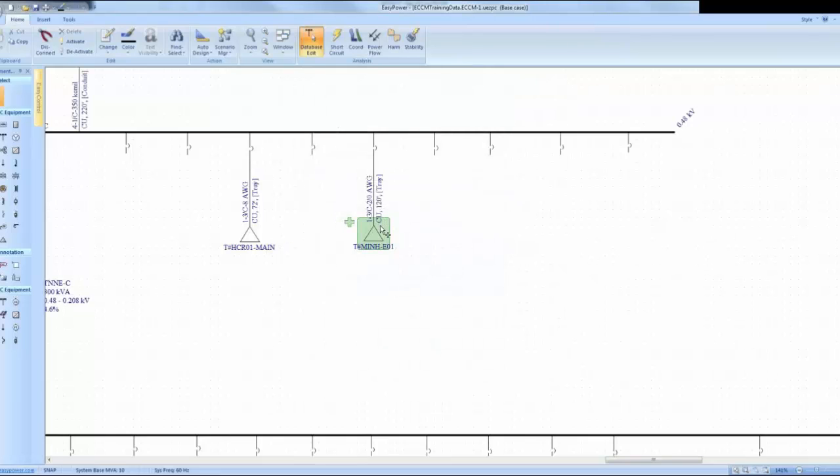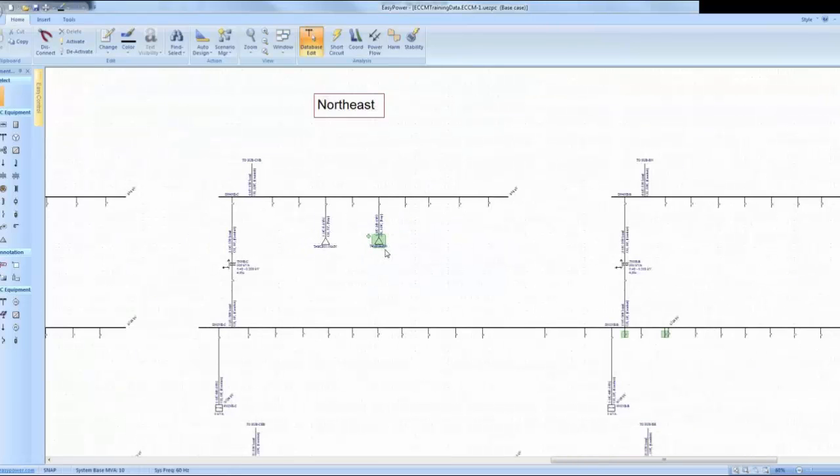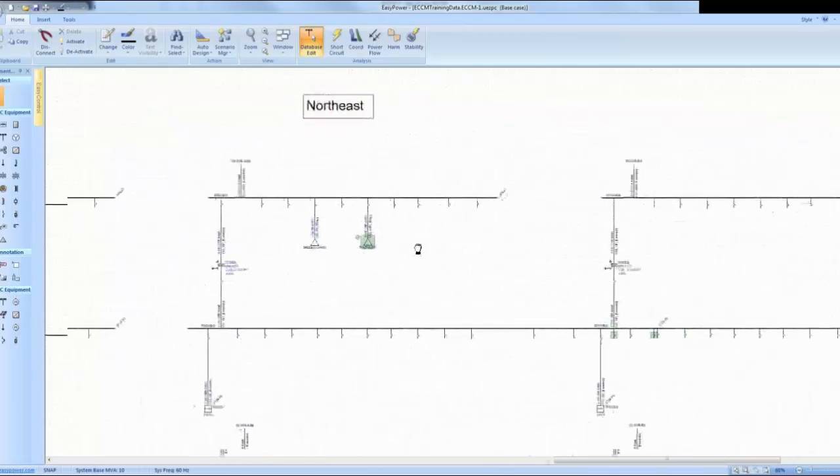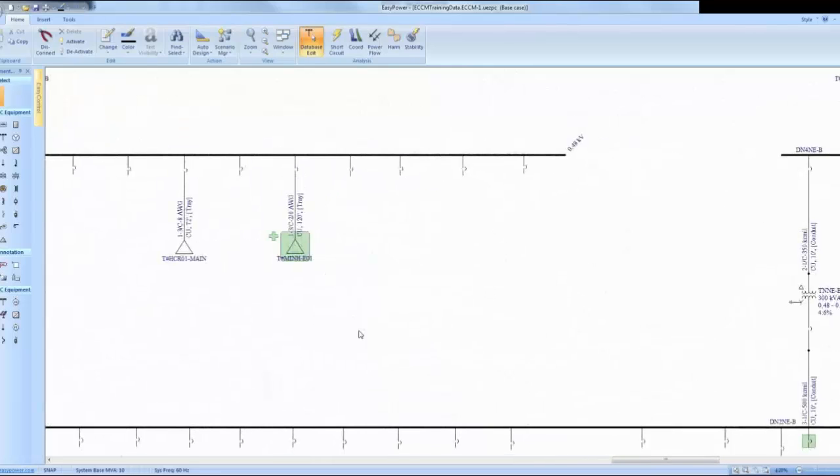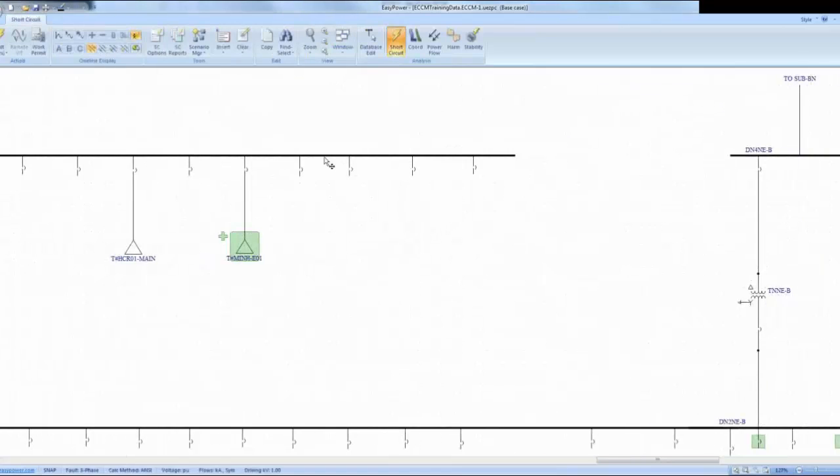What's nice about this, though, is now, as the electrical engineer and person responsible for maintaining the facility and the power, you can see when you open up the one line, this change request, go in and now validate that electrically this is acceptable. In this case, we'll switch to short circuit mode, arc flash, and fault this. And quickly, we get the arc flash calculation for this new tool. And then we can verify, generate new labels as necessary, verify this is acceptable within the system, perform coordination, and so forth, and ensure that this is what we want in the system. There's no potential issues.